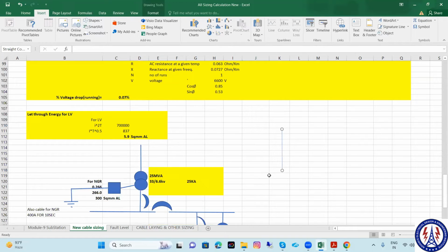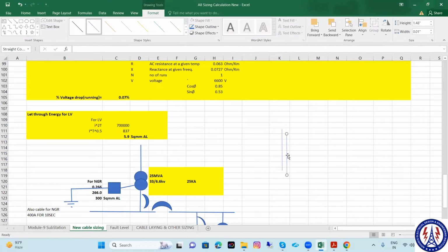Basically, you are telling from the PCC panel to the lighting distribution panel, right? Yes. Definitely, for the light load we are assuming that it is not possible to have a balanced system because lighting can be unbalanced. So in that case the neutral current will not be 50%. That's why we are just increasing the neutral conductor size.